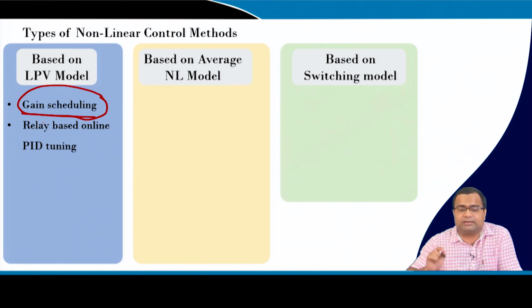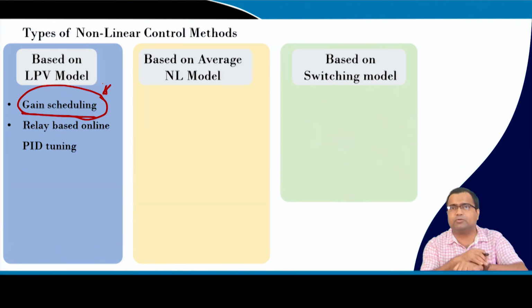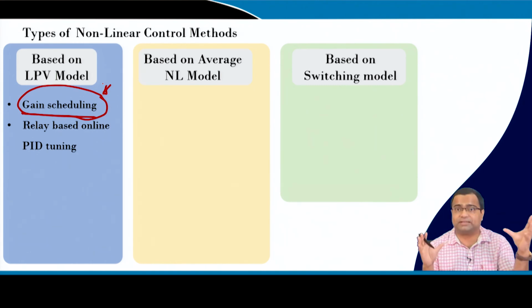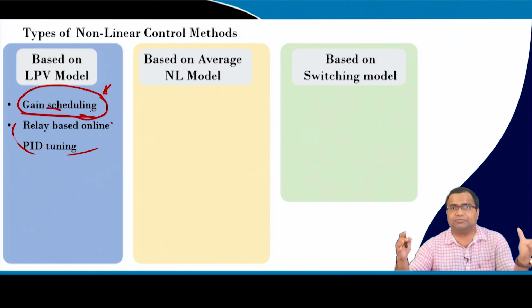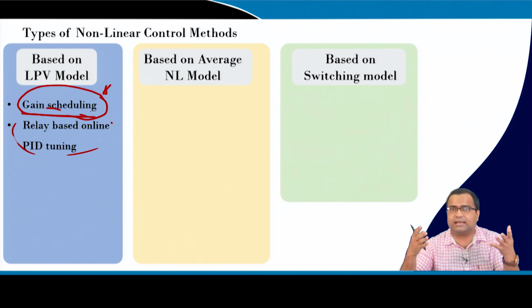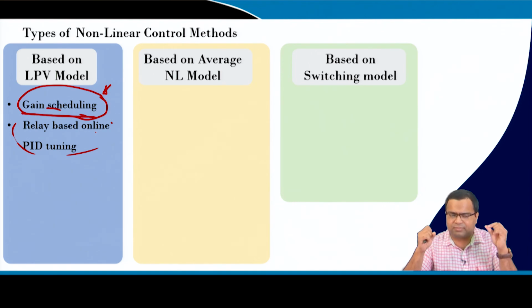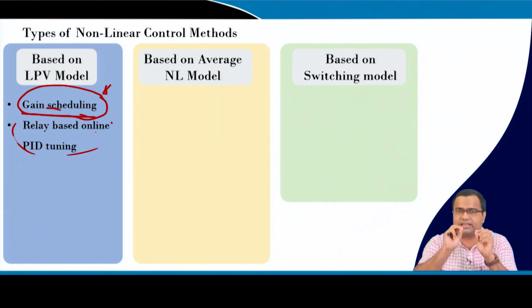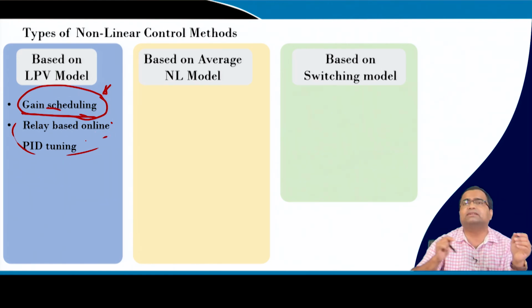Another is relay based tuning, but this is something like offline tuning, and you have to put a kind of lookup table and update the parameter. Whereas relay based tuning and something similar use online tuning. That means during the transient, in real time, you can create an event where you can insert an on-off nonlinearity, and using the control oscillation you can get the PID controller tuning parameters, and then plug them in to get the transient response.